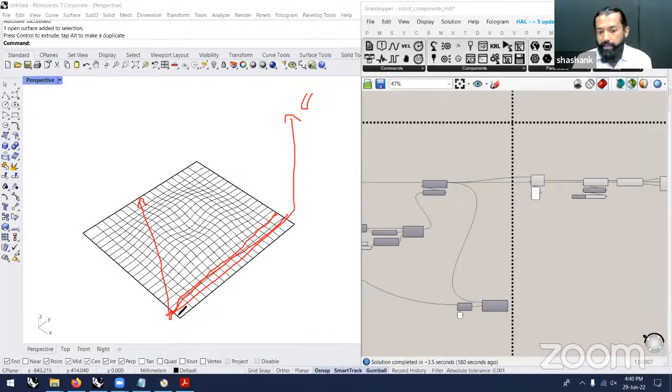And the other thing is, in the continuous set of points that you divided, if you were to create a line, you will notice that the points start from here and go all the way. And this is how lists are in Grasshopper. You'll have all these points, and they are named 0, 1, 2, 3, 4. Then what happens in the new list? The next set of lists again starts from here, 0. So this is the complete row of 0s. This is the complete row of 1s.